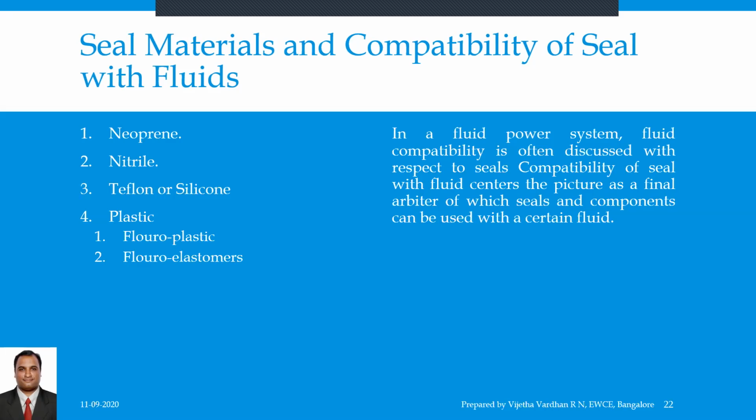Most oil seals in contact with oil are made from nitrile rubbers. Other materials suitable for oil systems include neoprene, silicones, and fluorocarbon rubbers. Most tubing and fitting manufacturers present extensive tables of materials compatible with their product specifications.